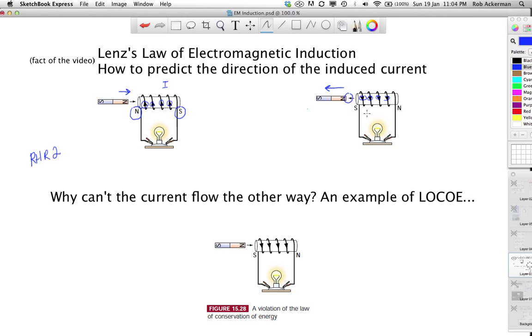So the way to do this is the following. If you've got something cylindrical, it could be a pencil, a pen, a can of Coke, anything, hold it in front of you the way this helix is oriented, and take your right hand and make your fingers point down, but not behind the object, in front of the object, because these wires and these arrows are on the front side, the side facing you.